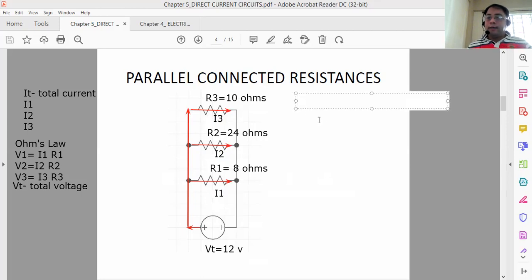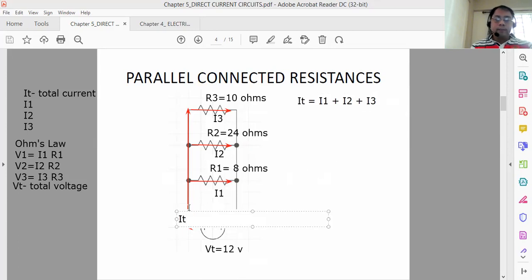So maybe with that idea, it will give us the first principle of parallel connection, which is that the total current that is provided by our circuit will split up into I1, into I sub 2. But when you add them together, they will simply combine themselves, and it will be equivalent to the current provided by the battery. So the battery current, which we call I sub t, simply goes in three different directions.